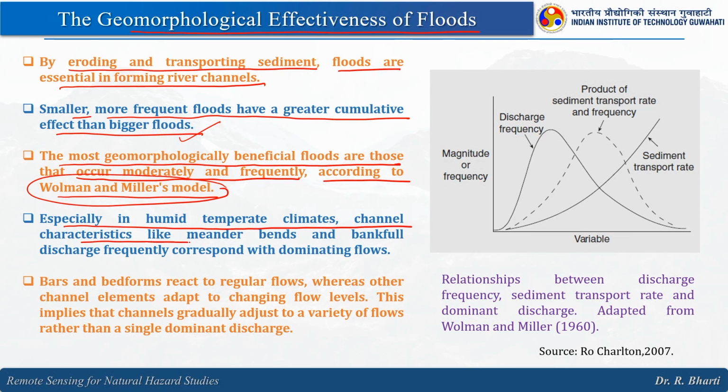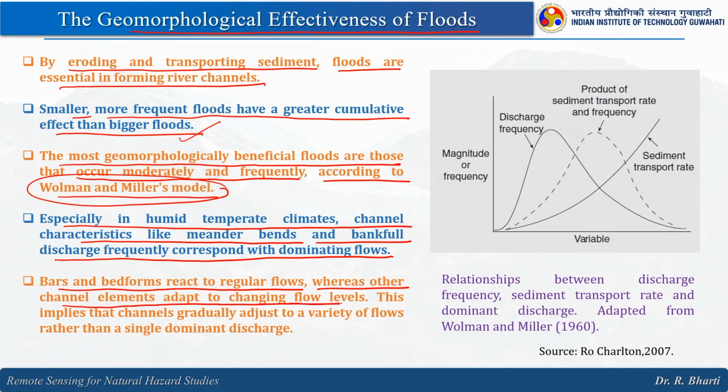Channel characteristics like meander, bends and bankfull discharge frequently correspond with dominating flows. Bars and bed forms react to regular flows, whereas other channel elements adapt to changing flow level. This implies that channel gradually adjusts to a variety of flows rather than a single dominant discharge.